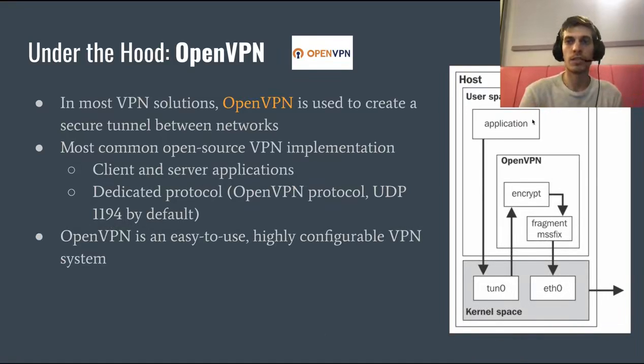We have this application, which is completely unaware of the VPN secure tunnel, but it needs to send data to what it thinks is a nearby device. So in our example, Rachel is using this engineering working station to send data to or read data from a PLC, which is actually at the remote location, but this application thinks that the PLC is nearby.